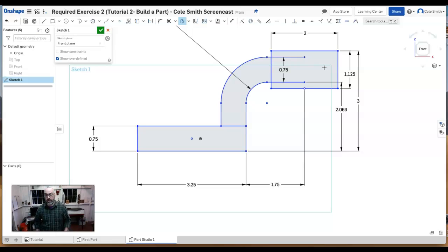There's just 2 more lines that I want to draw. I want to draw a line that goes through the middle of this box up there. That's going to be useful later on when I revolve this object. That's going to be my axis for revolving. So just trust me on this one for right now. Draw that little center line because we want to have a good axis to revolve. I'm going to hit escape.